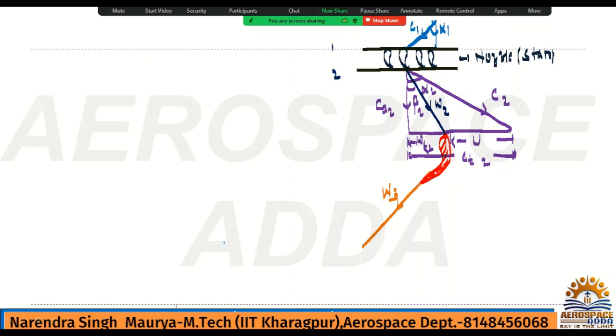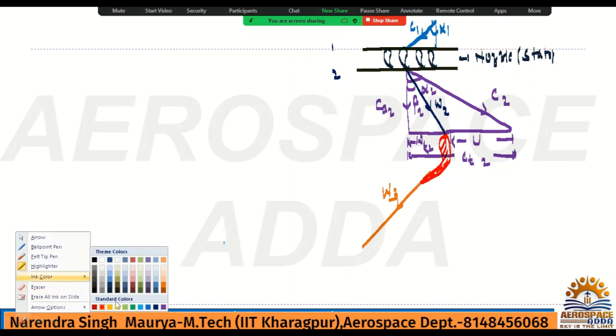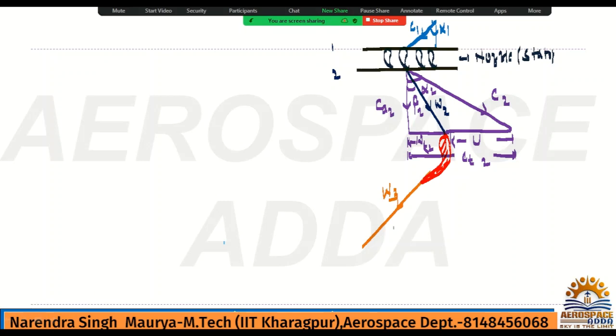All right. And the exit is what? W3. Now for this also we'll draw the triangle. So this is the relative velocity, and somewhere here we have obviously axial component, so this will be axial component, but it will be CA3. Somewhere we have absolute velocity as well, so this will be C3. From the axial, this angle will be beta 3, and this angle will be alpha 3.